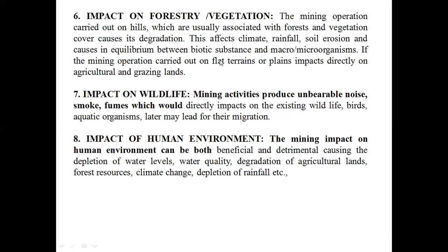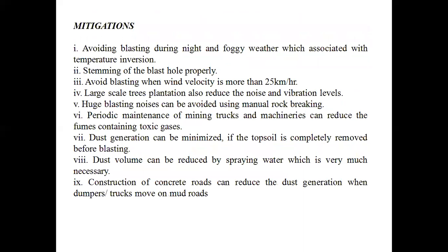So these are all the different things that we have to take care of. The mitigations related to that include avoiding blasting during night time, foggy weather, and temperature variations, and stemming the blast holes properly. The blast holes we create should be well stemmed so that noise pollution can be avoided to some extent.